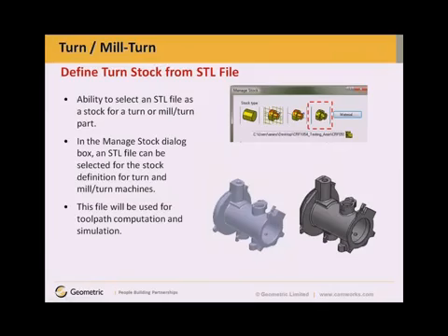Define turn stock from STL file. In previous releases of CAMWorks, we have had the ability to define stock from an STL file in the milling module. In CAMWorks 2010, we have extended this capability to the turning module and mill turn module.